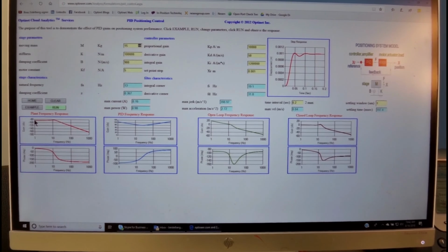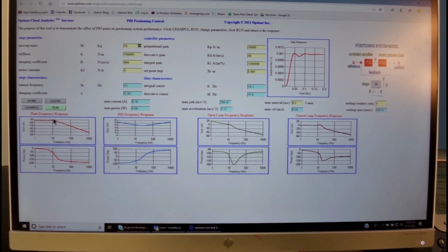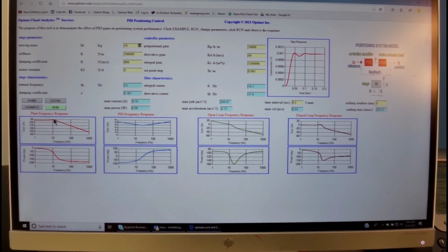What we'll see is that as we increase the frequency of the force, the output is going to follow exactly without any overshoot. However, at a certain frequency, the amplitude is going to be amplified, and this is the resonance frequency. As we increase the frequency of the input to the plant further, the output response is going to decrease.